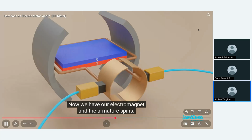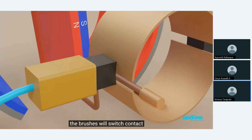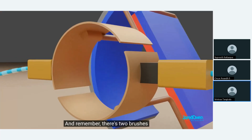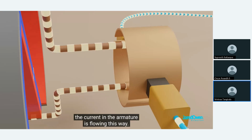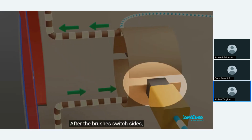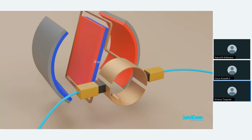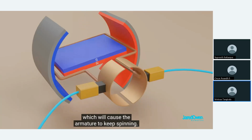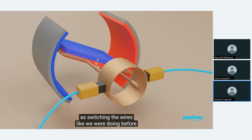This is called a commutator with brushes. So to pass the current in two different directions, we use the commutator, with a brush which is in contact with the commutator, which is spinning. So that way the current direction keeps changing with every rotation. This means that the polarity keeps changing in the electromagnet, in the armature.